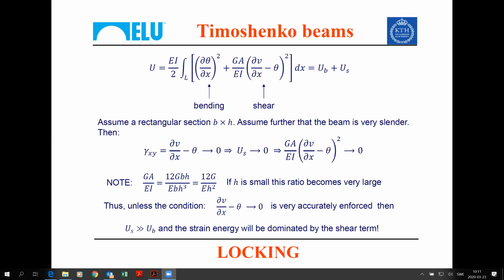Yes, sure, of course, because you have less bending stiffness, with the constant loading we're talking about. Then you say, okay, L over H is now 500. And then all of a sudden you see that L over H equal to 5,000 gives you a displacement which is much smaller than what you got for L over H equal to 5.